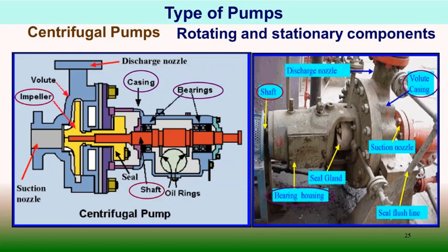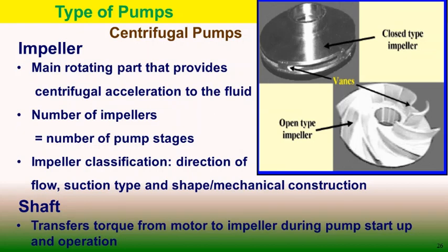A centrifugal pump is one of the simplest pieces of equipment in any process plant. Liquid is forced into an impeller either by atmospheric pressure or, in case of a jet pump, by artificial pressure. The vanes of the impeller pass kinetic energy to the liquid, therefore causing the liquid to rotate, and the liquid leaves the impeller at high velocity. The impeller is surrounded by a volute casing, or in case of a turbine pump, a stationary diffuser ring is also available.